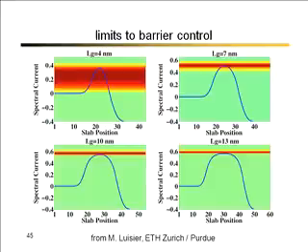Well, we've left out quantum mechanics. These are some simulations with a quantum transport model of a MOSFET, where we're showing the energy resolved current. The vertical axis is energy. The horizontal axis is position. So here's the source, here's the barrier in the channel, here's the drain going down here. Red means this is a ballistic device. It tells us where the current is flowing in energy.